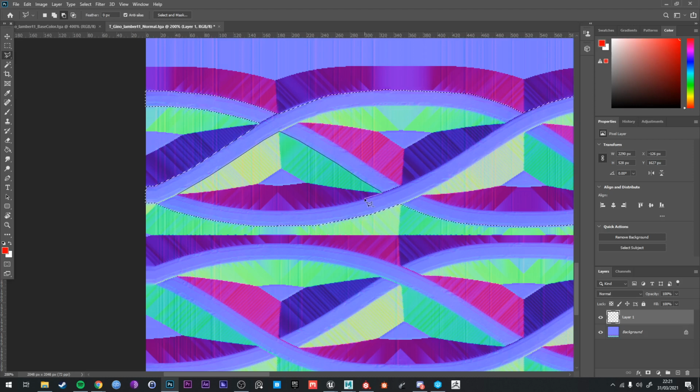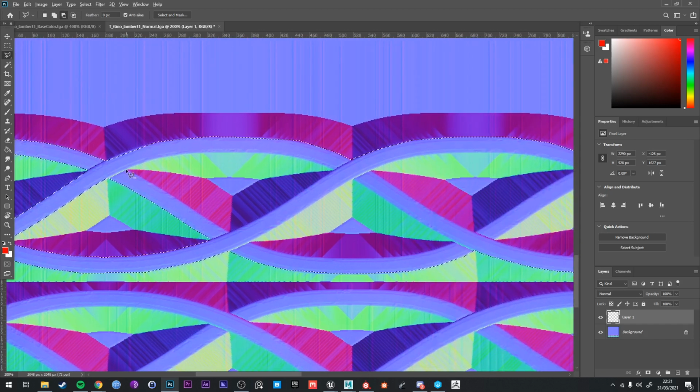So back in the day when people made masked foliage textures in Photoshop, well, I believe people still do actually, you can manually add dilation in Photoshop for that purpose. It's pretty cool. But yeah, people sometimes wonder, like, what is this weird smudged pixels I'm seeing on my texture? And that is, it's called dilation, and it's there for a reason.